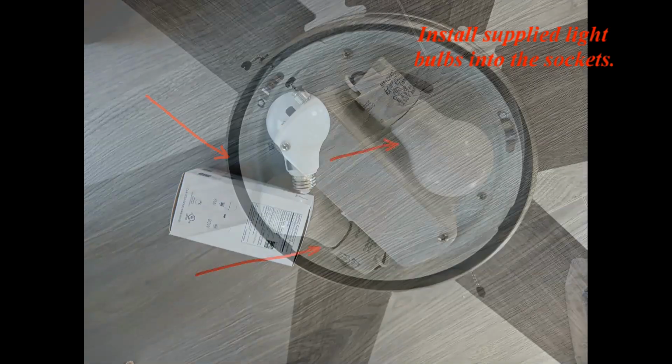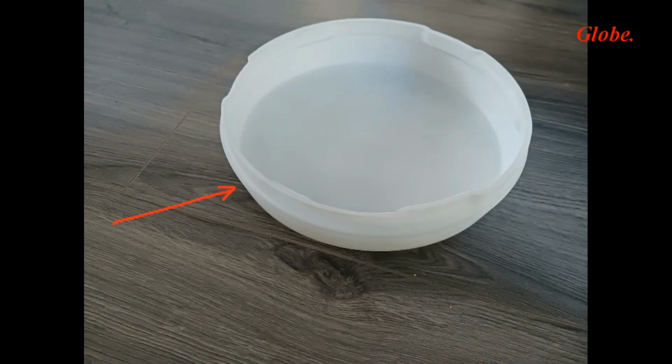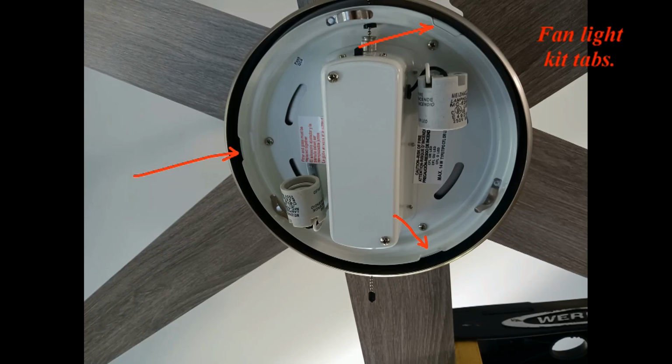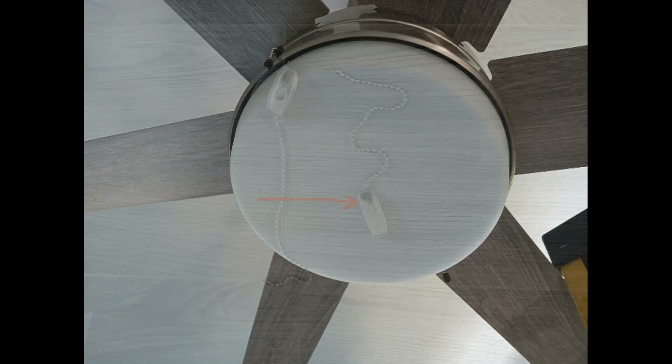Install supplied light bulbs into the sockets. Never install light bulb exceeding wattage provided on the label. Globe. The globe notches. Fan light kit tabs. Align the notches in the globe with the tabs in the light kit. Lift the globe and turn clockwise 1/3 of the full turn until it stops. Check to ensure that the glass is properly secured.